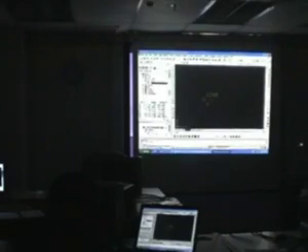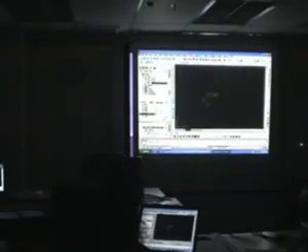If I want to modify the description for this, in Land Desktop I would go to Points, Edit Points, Modify and so on. Here all I need to do is click on the points list for that point, change this, let's say I put 3. Modify it, right?